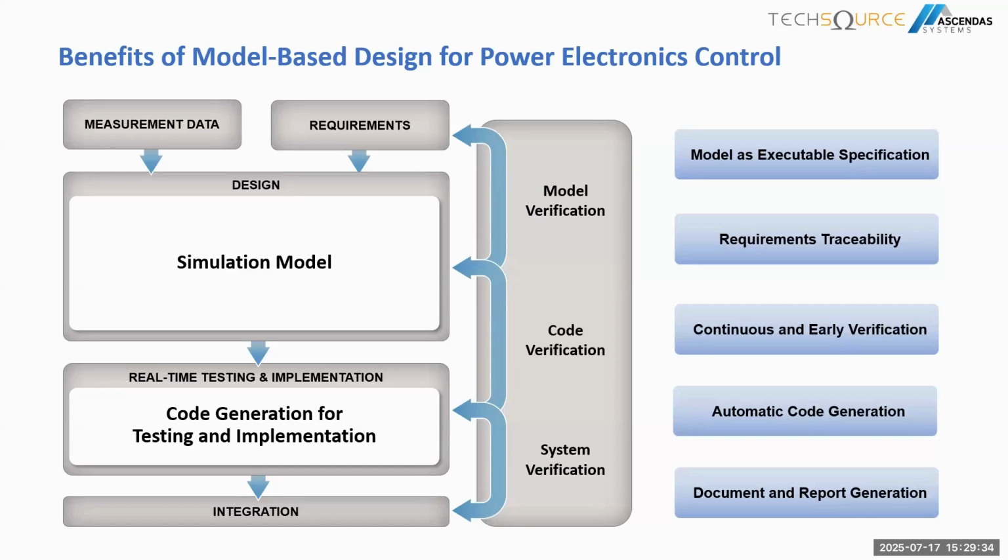There are tools that help you develop and verify your control systems and signal processing algorithms. This helps us reduce the time for testing embedded software for your control by generating code from the model itself. So in Simulink, you have a control model, and you can generate the code from these models, also to meet compliance requirements. This helps us certify the code to industry standards.